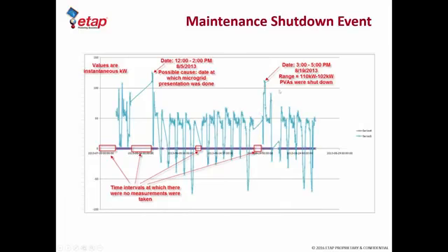So this is again just another example that you have to make sure that any maintenance or any outages are prevented during peak operating time, because once you have an outage, you will hit the kilowatt demand and the corresponding charge, and that applies for the whole month, and it kind of negates the benefit of having the PV array system.